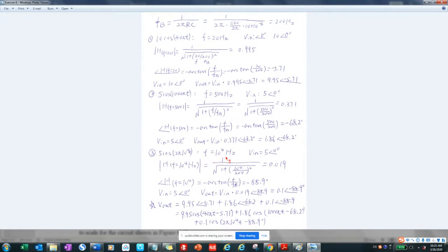This frequency is very high. As we said, usually we think that the low frequencies are the signals, the high frequencies are the noises, most of the case. So we know that these most probably are the noises, and we are using the low pass filter. We get the output from the capacitor.